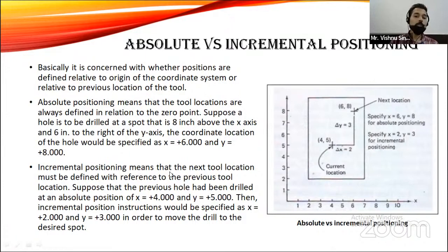Now incremental positioning means that the next tool location must be specified with reference to the previous tool location. Now suppose that the previous hole had been drilled at an absolute position of x4 and y5. Now suppose we have already drilled a hole at x4 and y5.